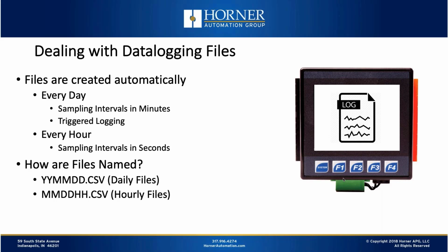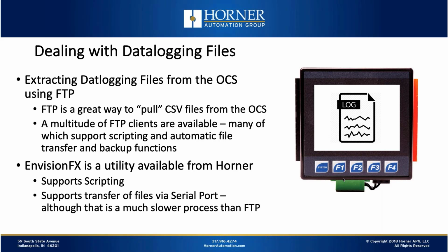Now, in terms of how the files are named, since every data log group has a name, all data log files are contained within a group folder, so that's how they can be separated, if you will. If the file is created every day, the year, month, and day are included in the file name. If the files are created every hour, the month, day, and hour are included in the file name.